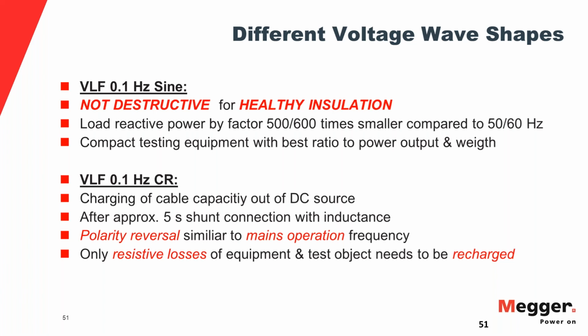And that has very interesting features. I will show you a picture later on if you haven't seen the other webinar. So that is one of the VLF waveforms. And then there's the sinusoidal VLF, the 0.1 hertz sinusoidal. Both VLF waveforms are also suitable from a theoretical point of view because their reactive power demand is so much less. So it's kind of damped AC. You need a fairly small DC source to charge the cable and then cause the resonance. So you don't need a lot of power in the field to charge the cable to do the testing.